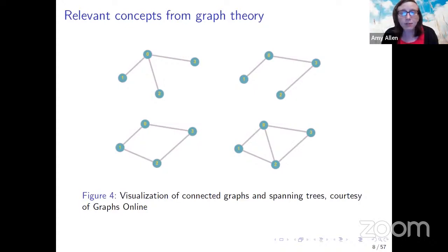And within spanning trees is the concept of a minimal spanning tree, or the spanning tree with the least total edge length. And one can see in the context of district thermal energy systems, the minimal spanning tree would provide a required level of network connectivity for buildings in the district, while minimizing the total length of thermal connections or pipes, thus minimizing that component of the infrastructure cost. So the minimal spanning tree graph becomes an important consideration in this context.